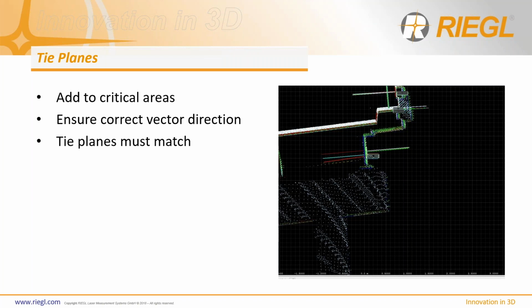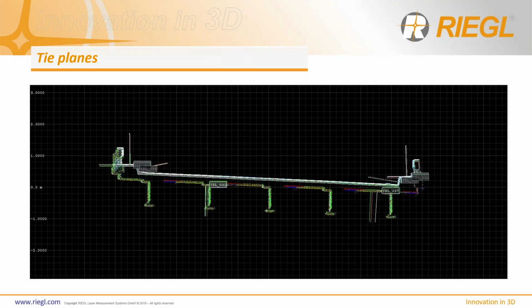So be careful not to make the area selection too wide. I did a few sections like this on the bridge as an example for this webinar. I selected the curbs, the top of the sidewalks, and I did some on the bottom here. I don't think they're really necessary on the bottom of the bridge, but I like to have a clean cross section on those I-beams when I check it post-process.